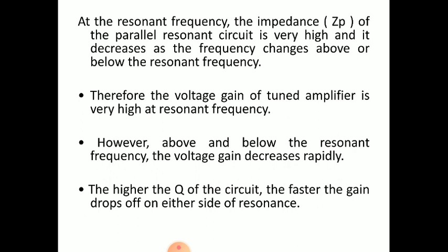That is when it will become 0 at a particular frequency f, called f0, the resonant frequency. If you want to calculate the resonant frequency formula, you should assign that imaginary part, the reactance part, to 0, then you will get the equation f0 equal to 1 by 2 pi root LC.